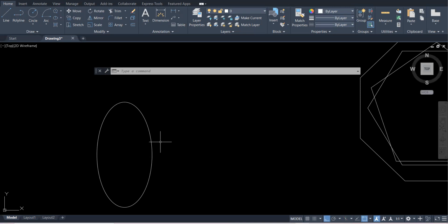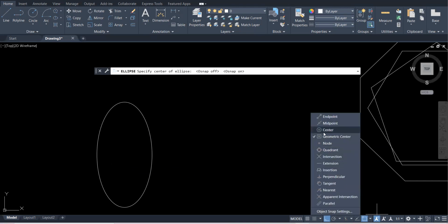All right. So another way, I'm going to click again and click the center. So this is the center. I'm just going to try to hover to find the geometric center. Now the geometric center, if it's not displayed, this means that I need to find this center. So I'm going to come here to the object snap, click, click again and right click with the mouse tool. And then I'm going to go to center.